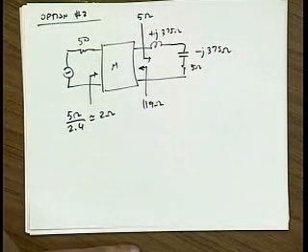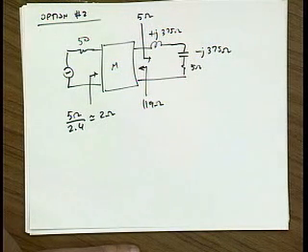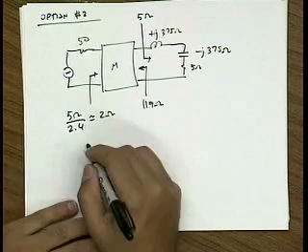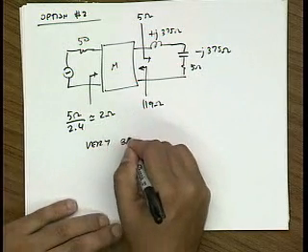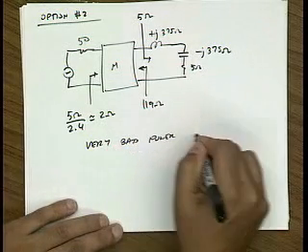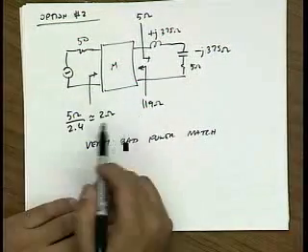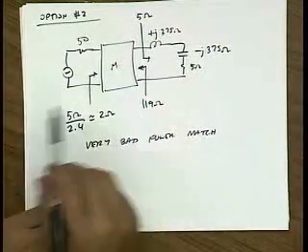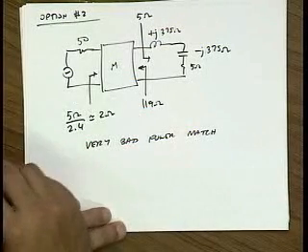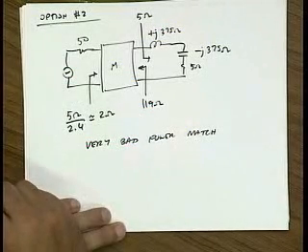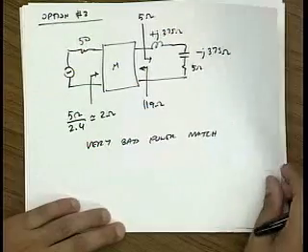Okay. Well, have I really done anything better, right? This is just as bad. So again, I have a very bad match. The filter now sees 2 ohms instead of 50 ohms. And if you take into account the voltage divider, you're losing a lot of power, right? Most of the power is being reflected and not going into your transistor. Okay?